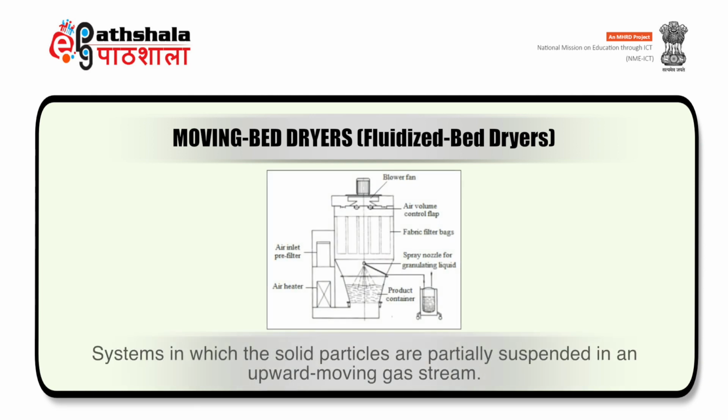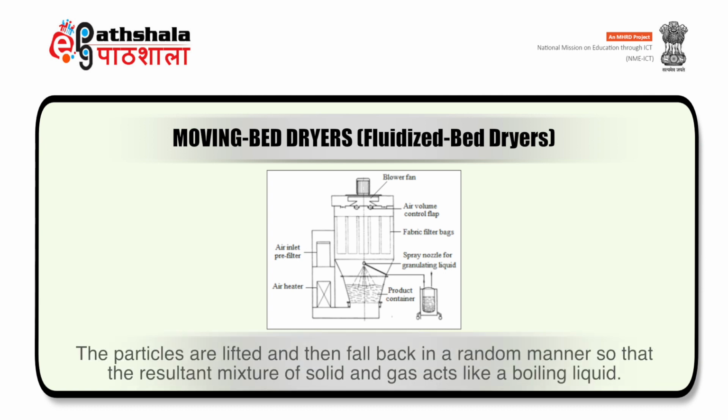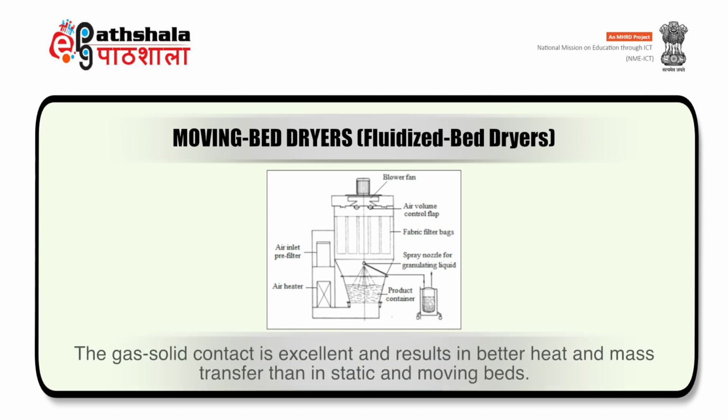These are the systems in which the solid particles are partially suspended in an upward moving gas stream. The particles are lifted and then fall back in a random manner, so that the resultant mixture of solid and gas acts like a boiling liquid. The gas-solid contact is excellent and results in better heat and mass transfer than in static and moving beds.